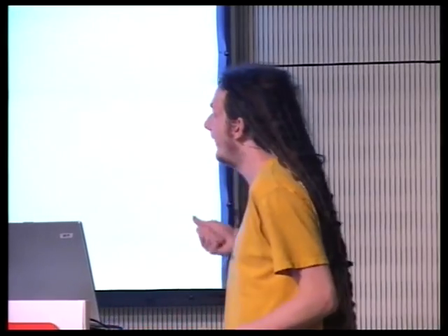As long as you don't overrun or underrun this counter, you can choose any odd baud rate that you like. If you speak to it at 9600 baud, it works fine. 9605 works fine. 9700 works fine. And because of this, you can make it speak more quickly or more slowly than it's supposed to.